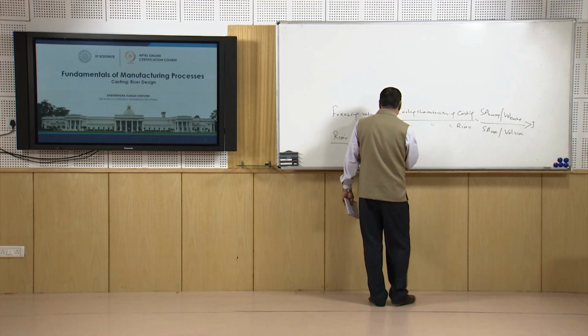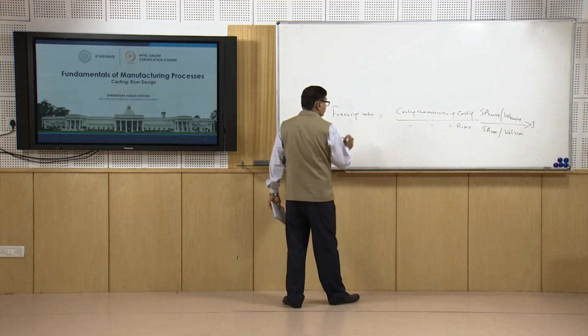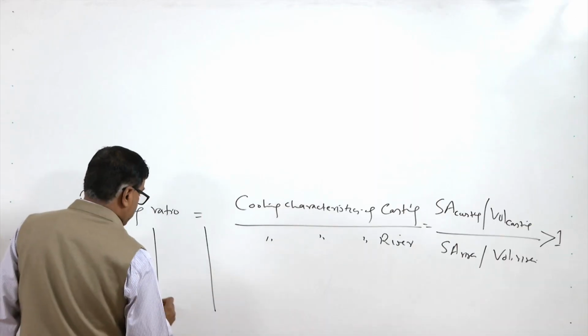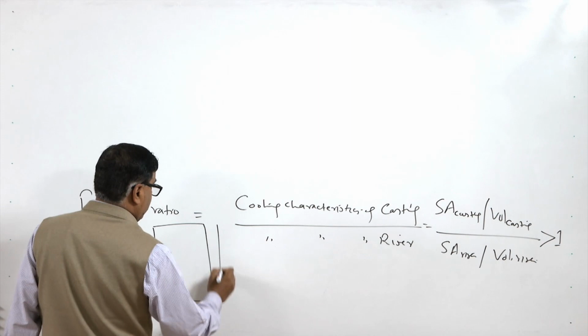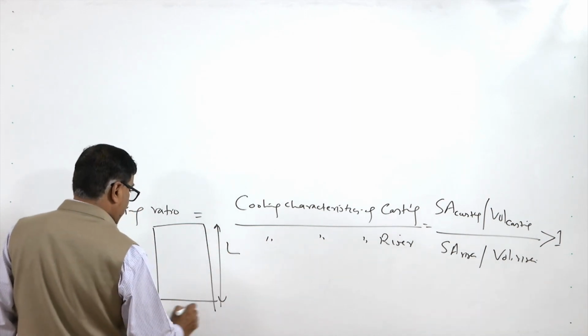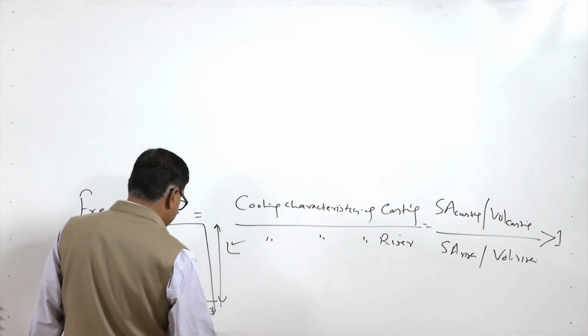So, this is found to be difficult to implement as a riser shape. The next preferred shape for the riser is the cylinder. In case of cylindrical risers, the length and the diameter of the riser are obtained as far as the design is concerned.